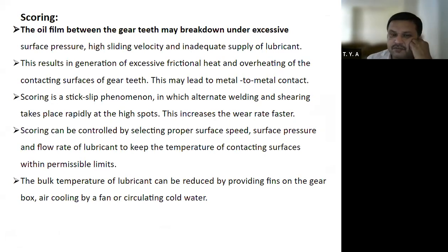The oil film between the gear teeth may break down due to excessive surface pressure, high sliding velocity, and inadequate supply of lubricant.